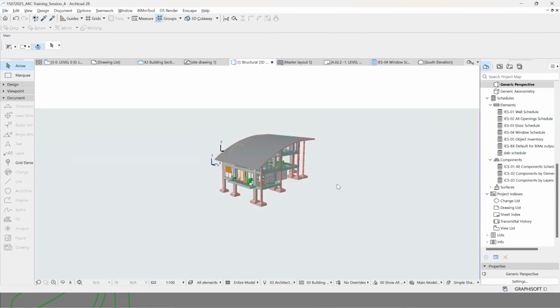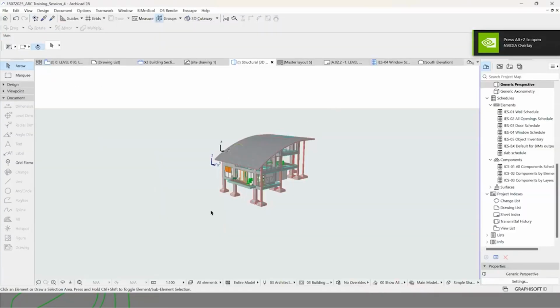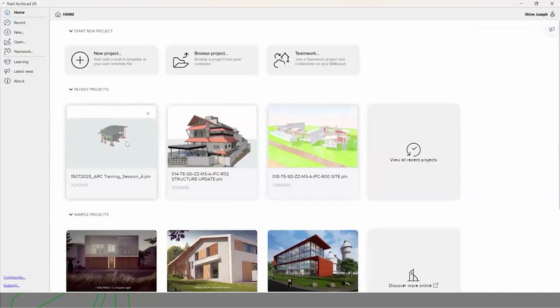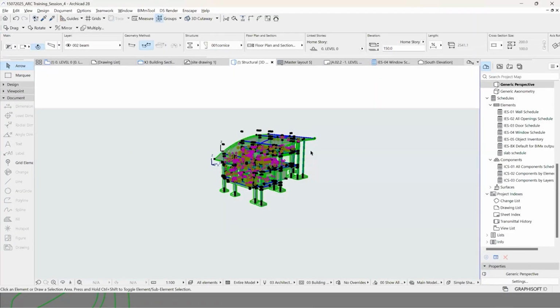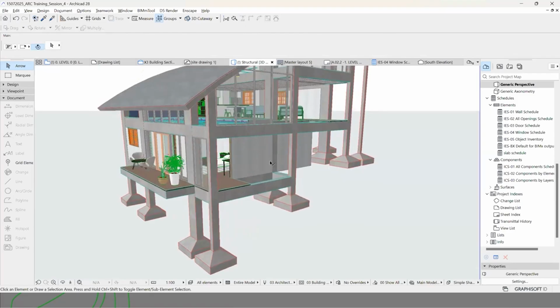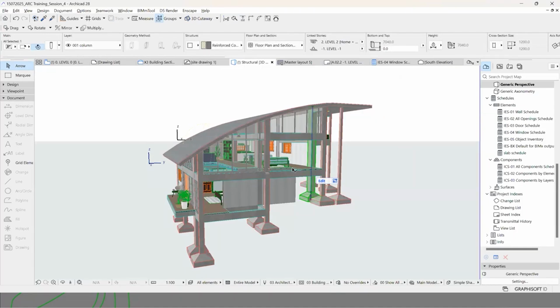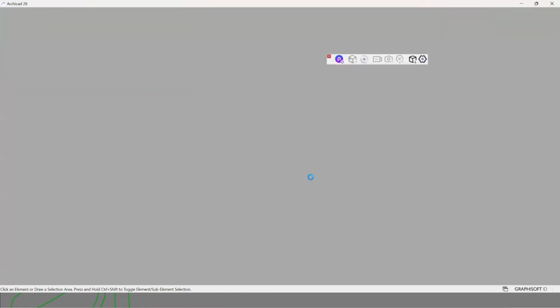And parallelly, the new ARCHICAD instance is opening. So let me click on new. So what I'm going to do is we have this as a source project. So ideally, I have to make sure that in the second project I have the site model done, or whatever context is done, because those are changing and varying. But this particular house typology might be consistent across. If something is going to change across your design, make sure it is not modeled here, because whatever you model in the source file, like for example this one, is going to be replicated there as well. So do it wisely.